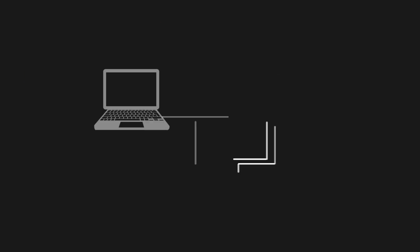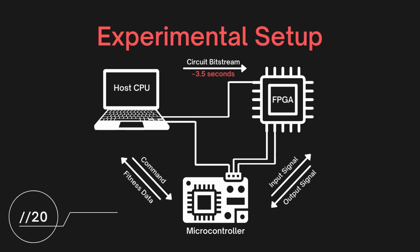Finally, let's take a look at our experimental setup. A host computer running an evolutionary algorithm will generate a population of candidate bit streams that are systematically uploaded to the FPGA to run for a period of time. Meanwhile, a microcontroller takes input from the FPGA's designated output pin and performs analog to digital conversion on the analog output signal. After capturing the waveform, the microcontroller transmits the ordered set of waveform samples over serial interface back to the evolutionary algorithm running on the host computer, where fitness is then calculated. An additional connection between the microcontroller and FPGA is in place for later experiments.